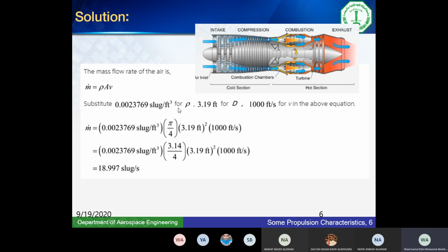The unit here is slug per cubic feet. If you use the slug, the foot, and the pound, there are no conversions. Just use them together as a British system, and the result will come out correct at the end, just like when you use meter, kilogram, Newton. So the density is 0.00237.